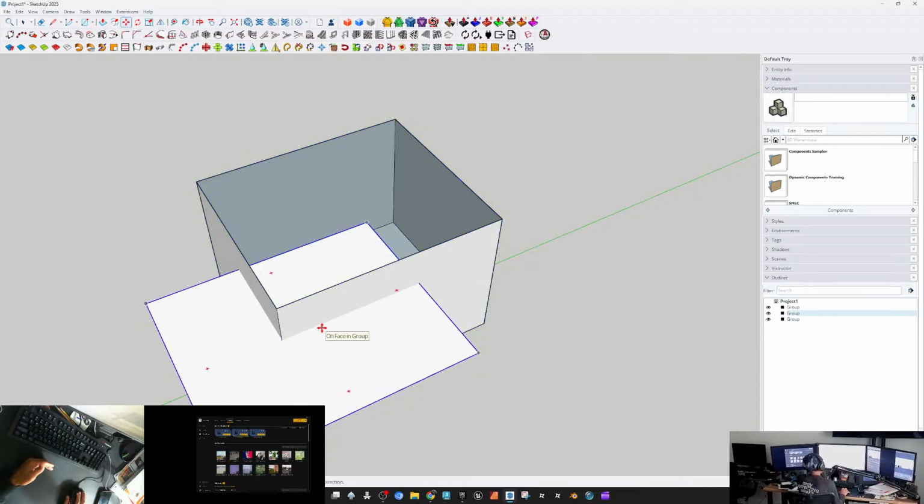One of the biggest problems that a lot of users in SketchUp face is that they don't group or create components for their assets. And when they go about moving components or entities around in their scene, sometimes those entities will attach to each other, making it hard to manipulate a particular set of entities that are meant to be separated.